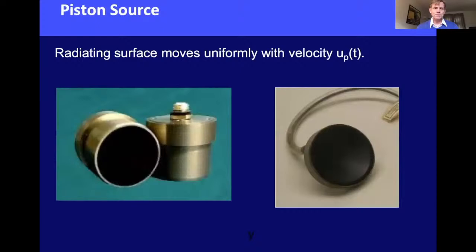Right, so now we're going to go on to looking at acoustic sources and the diffraction that happens when we have them. Most acoustic sources that are used for ultrasound use piezoelectric sources. This is a flat, unfocused transducer. It's a piezoelectric disc in here. You put a voltage across it, and it changes its thickness. As you oscillate the voltage, the thickness goes backwards and forwards, and so you actually get a velocity source at that piezoelectric material.